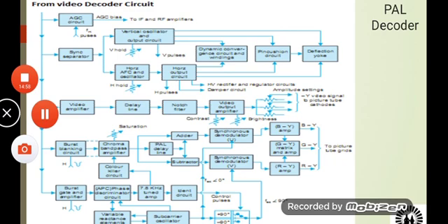whenever the signal comes back after striking every possible obstacle, the amplitude value of the signal should remain the same. That is because in a video signal the amplitude values continuously change depending upon the brightness value and the color value. If a signal strikes multiple obstacles and then reaches back to the antenna, its amplitude level may go down.